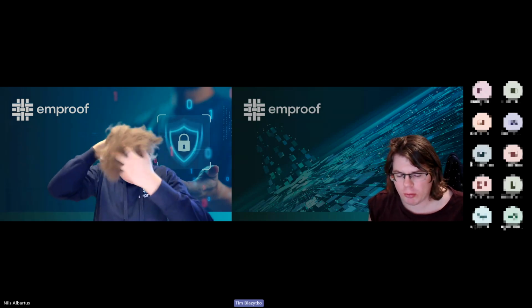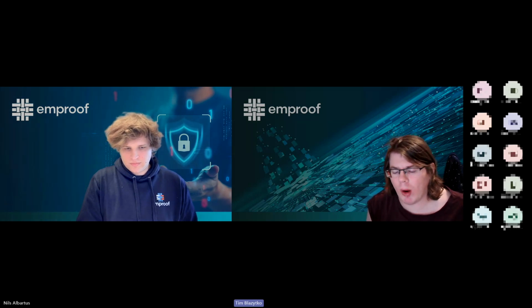However, in embedded, there's no way you can do that, because there you might have just some ROMs with limited kilobytes, like 64 kilobyte ROMs, for instance, in the worst case, where 50 kilobytes are used. So in this case, you can't do many factors like that. So what we do is we apply something around 10 to 15% overhead, depending on the configuration. You can configure in the profile how much overhead you actually want to have, and then Nyx decides automatically where and what to apply, so that you meet the overhead boundaries.